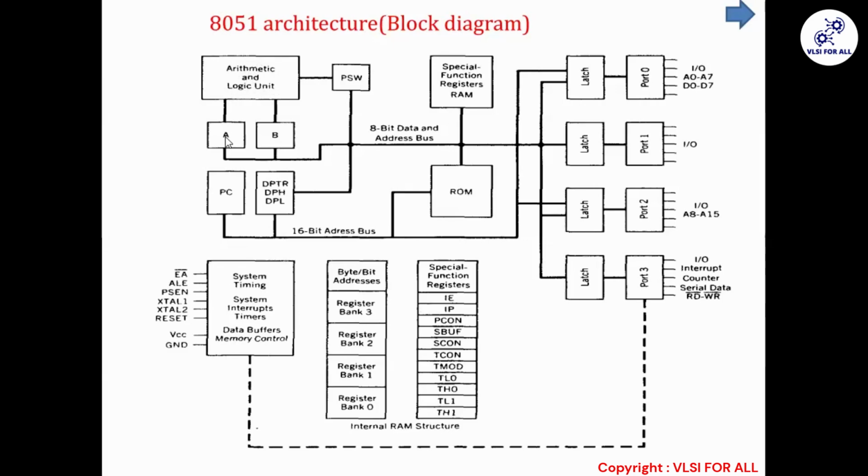It is supported by what? A and B. What are these A and B? A is the accumulator, which is a register. How many bit register? 8-bit register. B is again an 8-bit register, which is the supporting register, storing the other 8 bits of data which have to be dealt with in this ALU. Now, whatever output you are getting after addition will get saved in A.